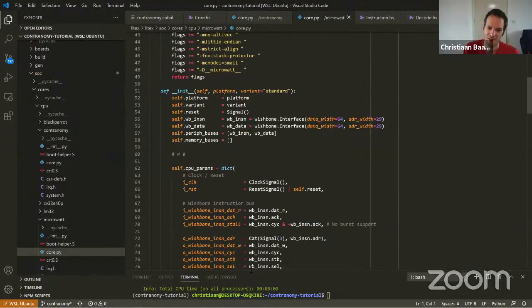I think in practice the answer is no, because you would have to write so much inside of this LiteX framework. The way it helps you now is that there are already all these kinds of peripherals, and what's nice is that there's a single Wishbone bus, and you can say, add this peripheral at this address and that peripheral at the other address, and it will create the master or the Wishbone switch automatically based on those addresses. So it really helps there.